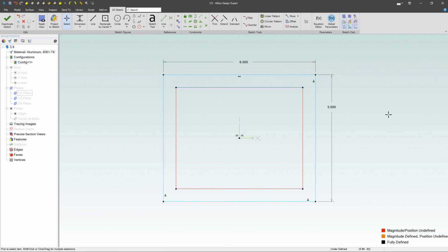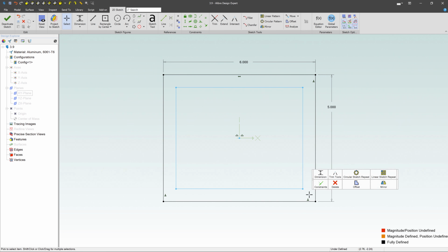And just that easily, you were able to kind of copy that exterior rectangle and bring it on the inside, and then you can use this to do things like laying things out. A very common thing to do would be to change this interior rectangle to a reference rectangle. So what you do is you select all these lines here. You say, hey, I want to switch these from regular geometry over to reference figures. Click on that, and now it's a reference. Okay, and then I can use this to lay things out.